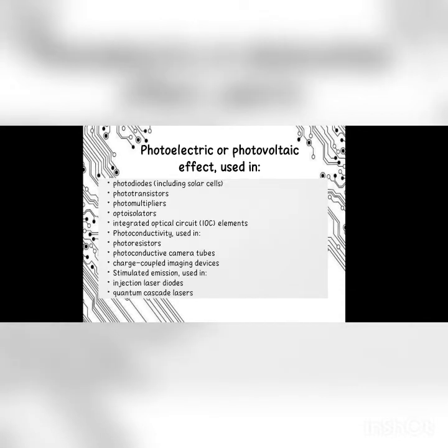The photoelectric or photovoltaic effect is used in photodiodes, solar cells, phototransistors, photomultipliers, optoisolators, integrated optical circuit (OIC) elements. Photoconductivity is used in photoresistors, photoconductive camera tubes, charge-coupled imaging devices. Stimulated emission is used in injection laser diodes and quantum cascade lasers.